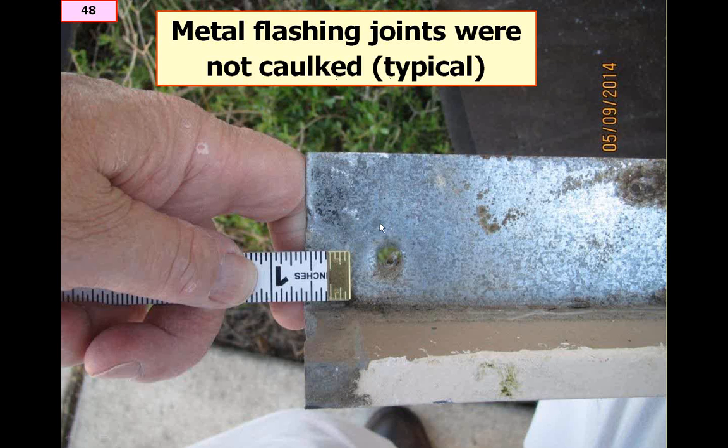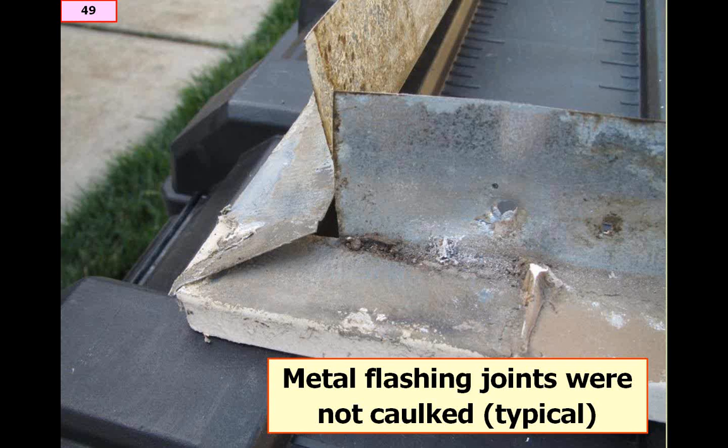these metal flashings at these transitions were not caulked. So the purpose of the flashing is to keep water from entering the building envelope, but because the contractor failed to caulk the joints, he allowed water to enter into the wall assembly behind the stucco, or behind the belly band, which then was heated by the sun, as we saw on the graph, and pushed into the wall cavity by solar pressure, by solar-driven diffusion.